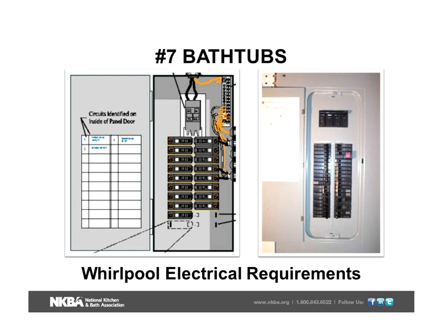On the right, you see a 200 amp panel that is stuffed. There are no circuits available on this panel to be added. No breakers could be added. Now, I know this panel personally. This is in my home. I've got a 2-bedroom home. The panel is stuffed. It is all electric. But I am not using anywhere near the electrical capacity. I'm using the panel capacity, simply the size of the breakers. But I could put a sub-panel in, so I know I could do that.